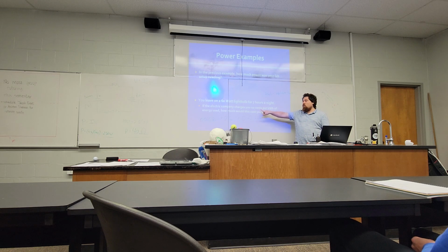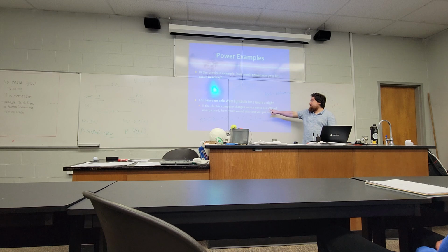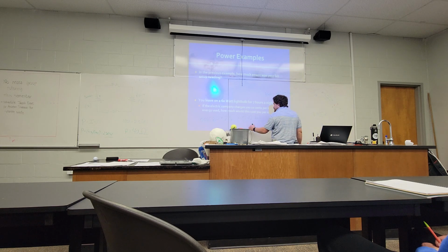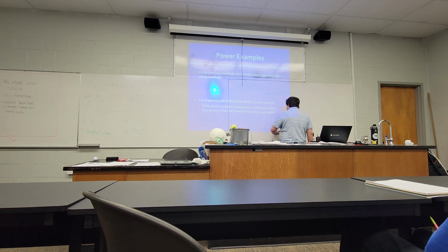Once you are aware of this rate, as the example, 10 cents per kilowatt hour, you can take the kilowatt hours of energy that you use, multiply it by the going rate, and figure out how many cents that device costs you per day. So we've got 0.42 kilowatt hours.